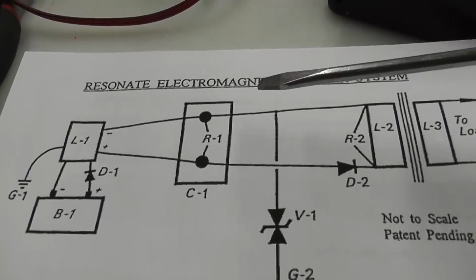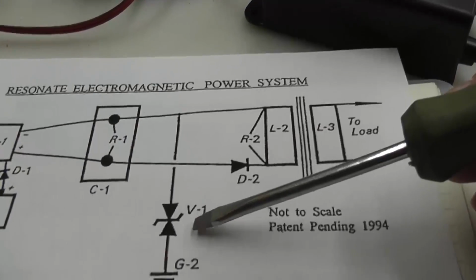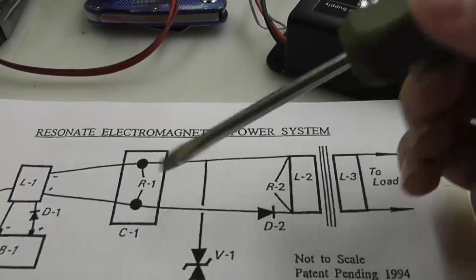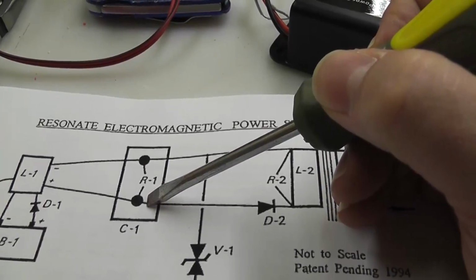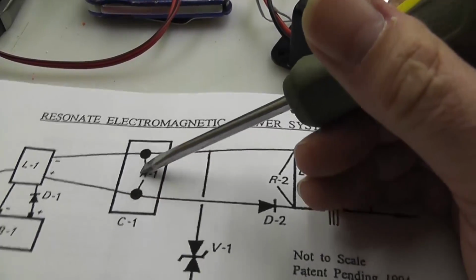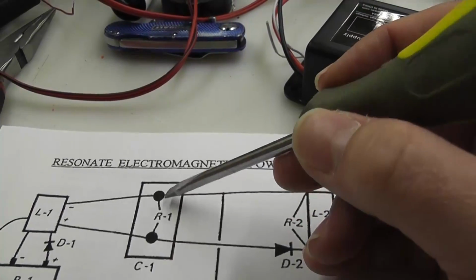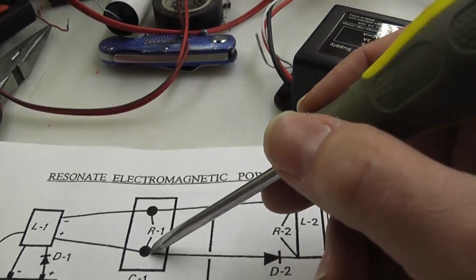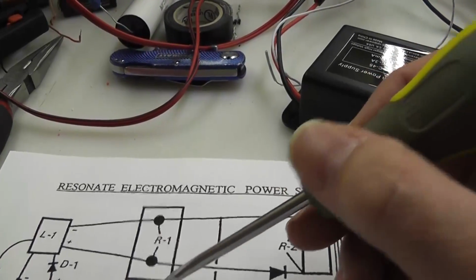The other thing that is interesting about this is he puts this diode over here and a varistor right here, which is going to do the same thing that this resistor does here. It's going to limit the voltage. So what happens is, if you put a resistor across this capacitor, you're only going to allow this capacitor to build up X amount of charge, because the rest of it just gets drained across here. So of course the higher the value of this resistor, the more this capacitor is allowed to charge up. Because if you imagine this was just a wire right here, then basically the capacitor never charges because you got a short, right? And as the resistance gets higher, you allow whatever that voltage drop is across the resistor to be across the capacitor.